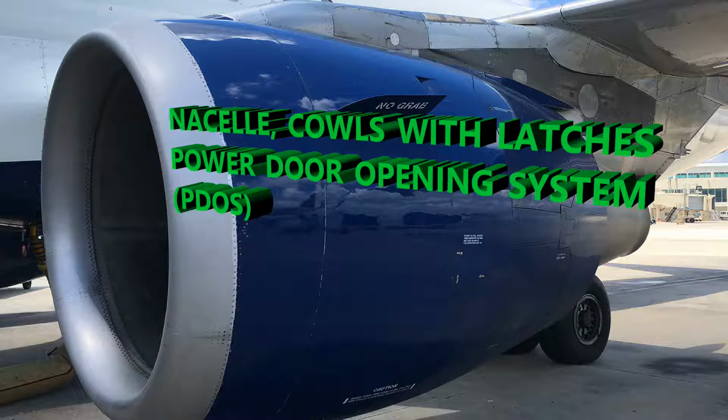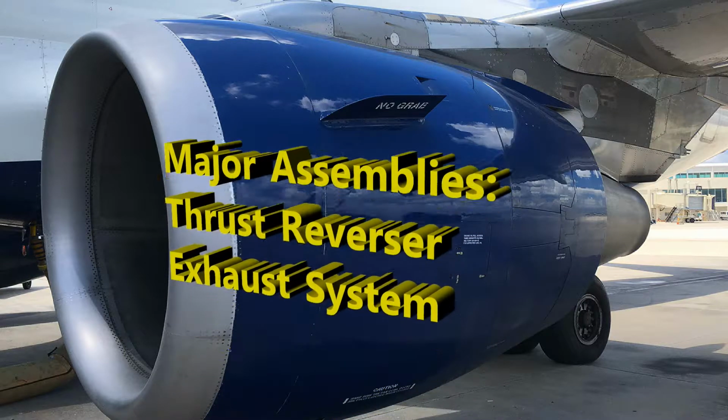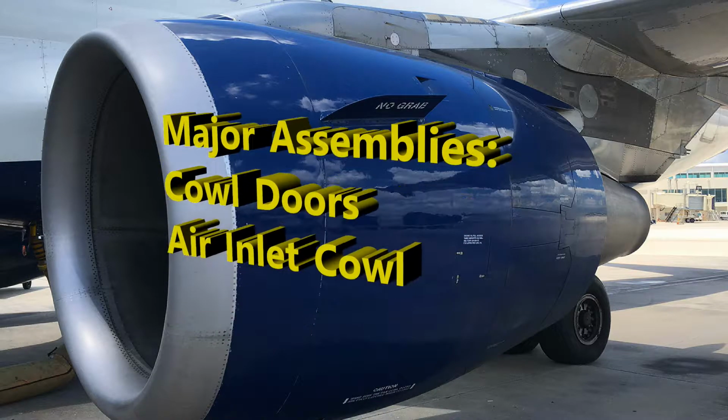The nacelle is simply an enclosure for the engine and all the related assemblies, and it is located under the wings of the aircraft. And the major assemblies, just to give you an idea of what we're talking about, you have the thrust reverser assembly as well as your exhaust system, of course your cowl doors. That's going to be for your fan cowl doors, as well as the cowl doors for the thrust reverser.